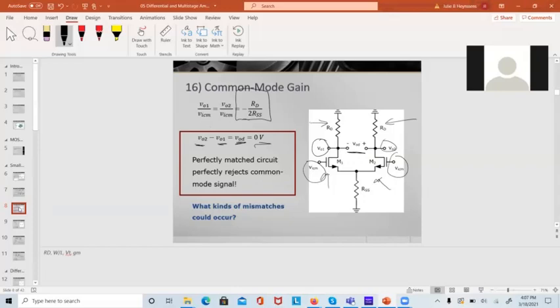That never happens. The way people fight this and get the common mode rejection ratio higher is by getting the matching on the transistors better across the process. So if you use larger transistors in a smaller process, like 100 nanometer transistors in a 5 nanometer process, you can make the 100 nanometers pretty exact, within a fraction of a percent.